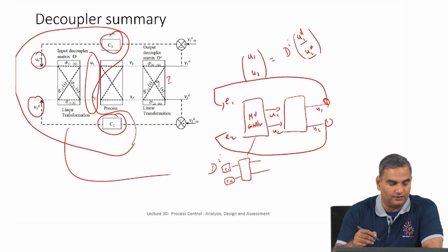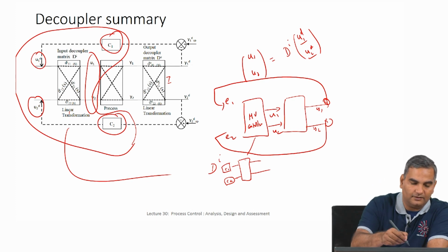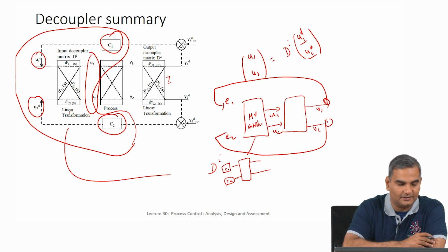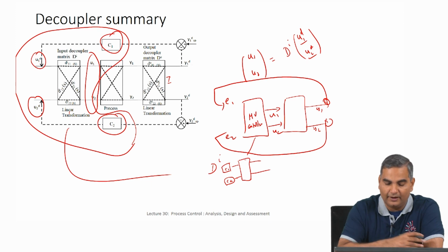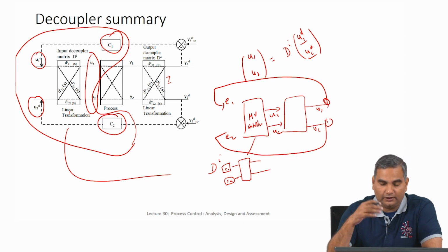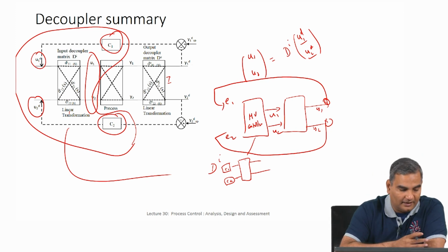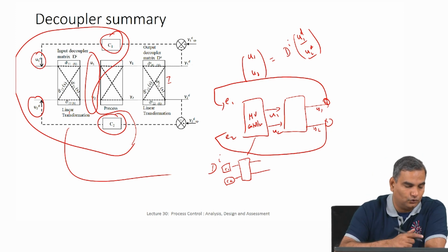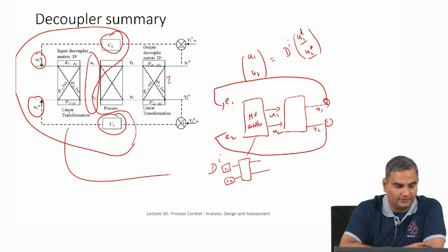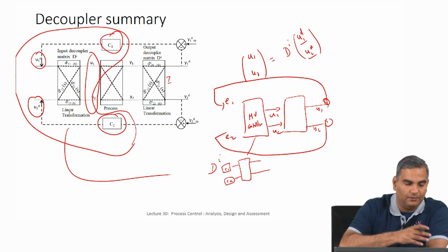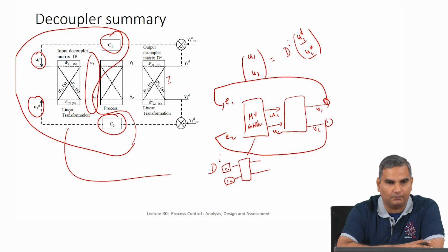However, the beauty of this is because we have done this, these controllers can be designed like single input single output controllers. Okay. So, again the notion of including interactions is beautifully addressed here, where we choose our decoupling matrix in such a way that we have a minimal effect, or zero effect if the models are perfect, of U1 decoupled on Y2 and U2 decoupled on Y1.